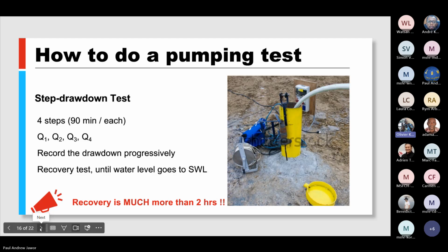This is going to be very fastidious for some people because it requires them to constantly record values. And when you ask this of some people, it becomes tricky and they don't like to do this. We are really trying to stress that it is very important to gather these values, because the more values we have, the more reliably we can interpret the results of the pump test. In some situations, we've seen that in one step of the pump test, people record 4 values and use these 4 values for their interpretation. This is generally not recommended.